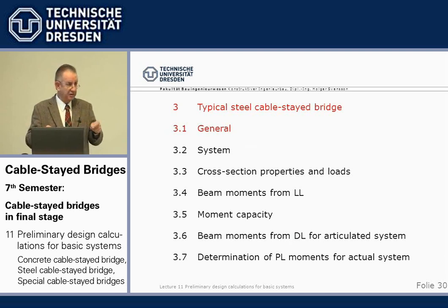And of course we had the normal forces for these, and we can combine them. We can calculate the stresses. We can, for the bridge beam in the center, superimpose post-tensioning, just the compression force, by, for example, the condition of no tension at the bottom and within the permissible range of compression in the top.